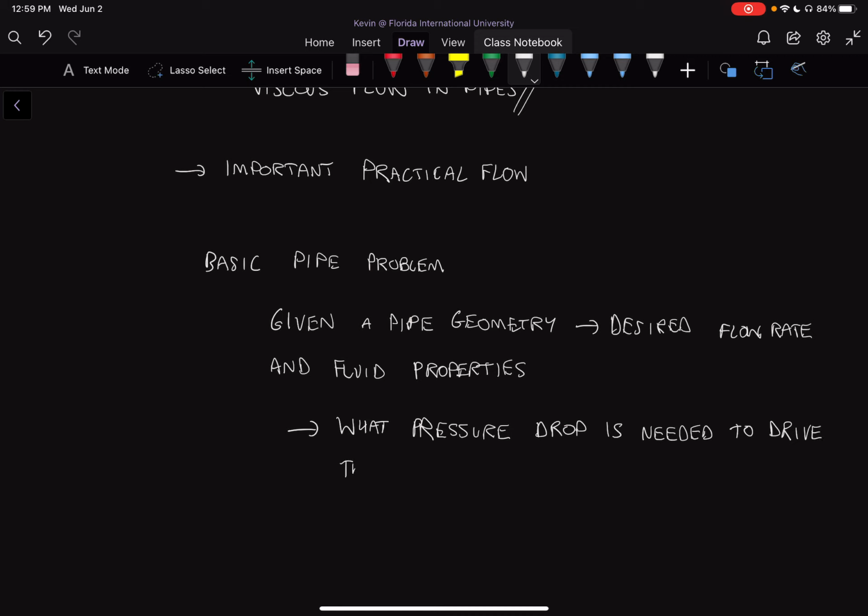In a second instance, we're also going to answer the question, what flow rate can we achieve? If we don't get enough flow rate, we need to go back to the drawing board and probably add more pressure, or change the piping so that there's less friction, or do some sort of design iteration. But this is a typical example of a piping problem that you would be faced with, and your example problems, as well as your study problems, will follow this kind of procedure.